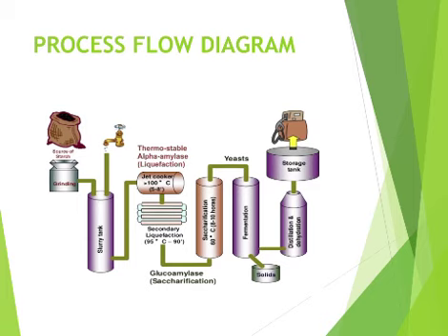So as we can see, this is our starch source. After grinding, it gets into the slurry tank where liquefaction takes place, and then to saccharification, fermentation, distillation and dehydration, and finally to storage. From cassava handling through to ethanol production and storage, this diagram reflects a real-world industry setup customized for Ghana and any other cassava-abundant region. Now to the computer needs of the process plant.